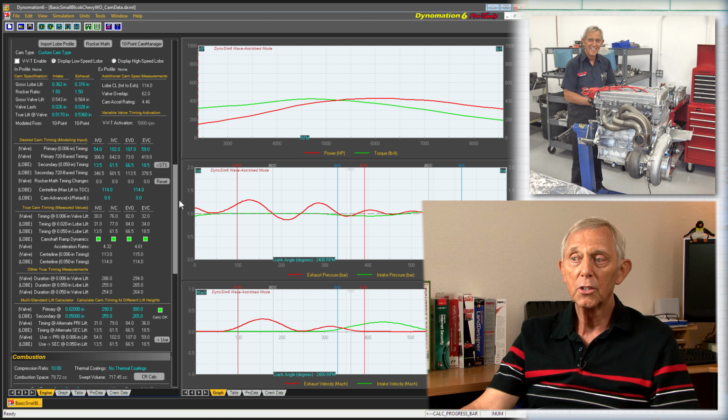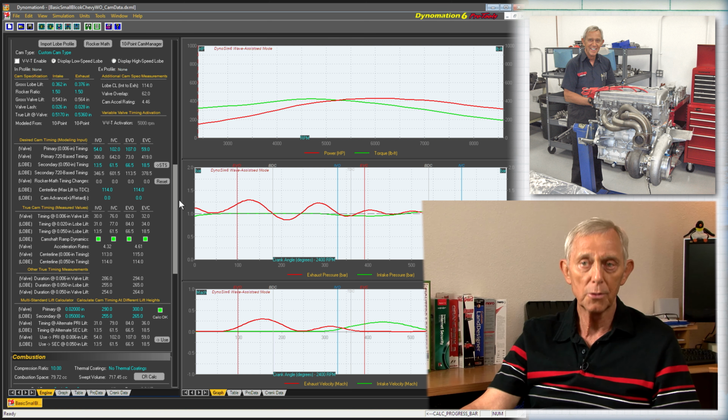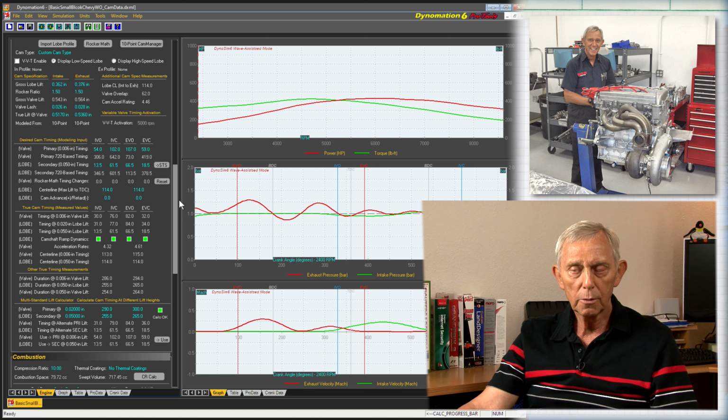And the other advantage is you have an open spring. If you need to, you could cool it very nicely. Let's say if you're on a motor up to 16,000, you can still run springs. Anything above that has to be pneumatic. But if you run springs, a valve spring will deteriorate very quickly if it starts to overheat. So if you need to, with the rocker, it's an open setup, you can cool the spring with an oil squirter very nicely. And that's also an advantage.